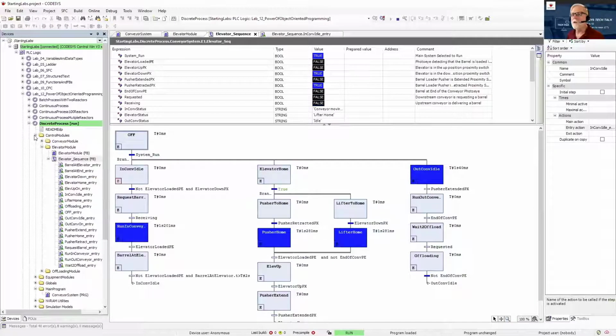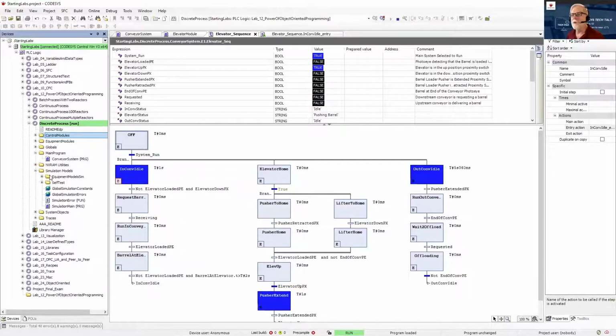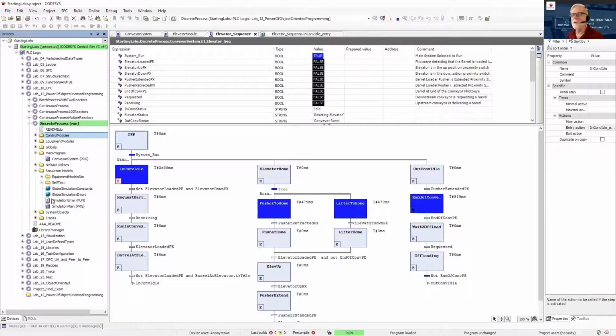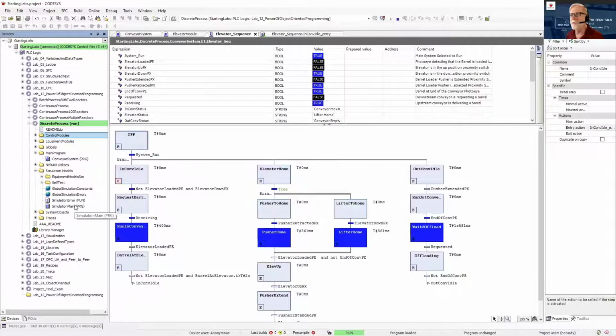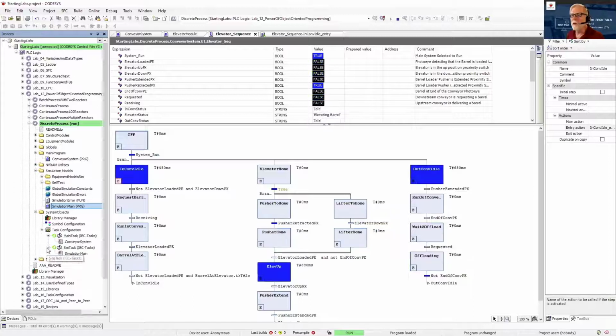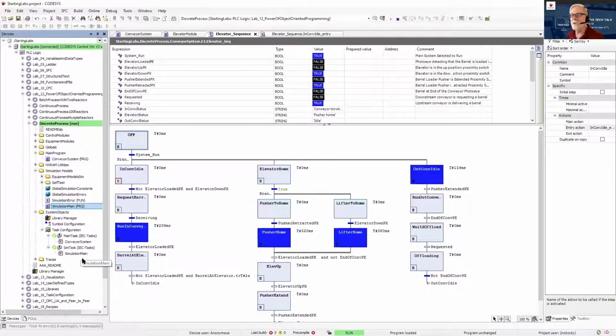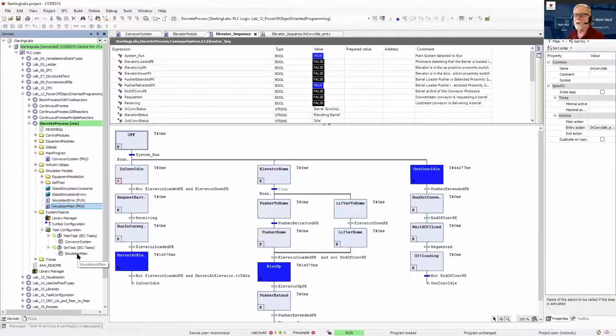Now let me show you just a simulation module. I'm a huge advocate of simulation. I've got a few more slides on that later on, but while we're here, I just want to show you. You'll notice, first of all, that generally speaking, I have 2 tasks, and one of them is for the plant, and the other one is for the simulation. That way I can easily take this out when it's time to map in the physical I/O, and just take the simulator out.